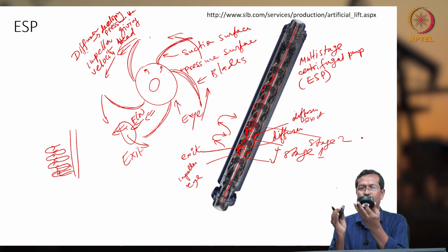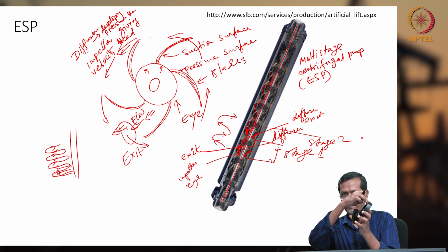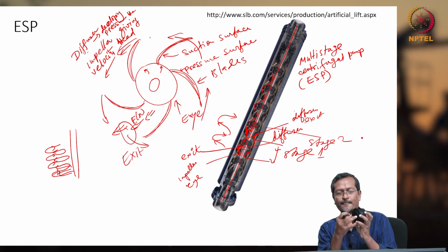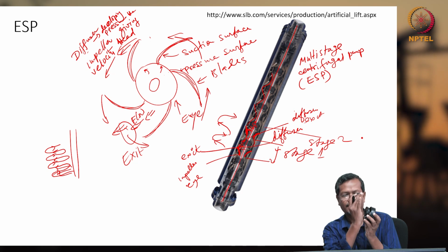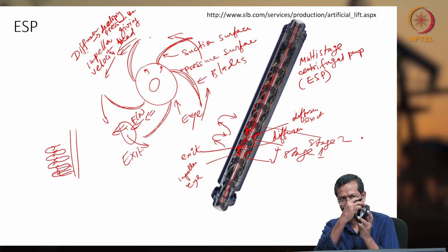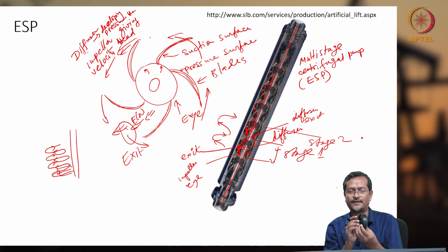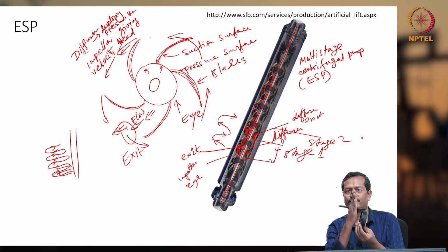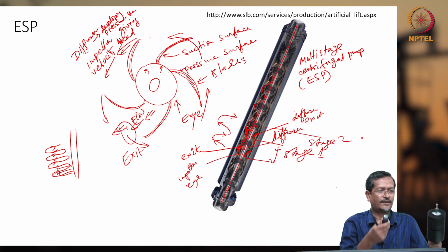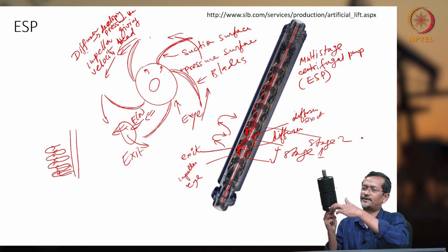I have the impeller, and the diffuser is this white part you can see. So fluid exits from the impeller, then enters from the top of the diffuser, and goes nearby the shaft. It will be connected like this. The impeller sucks fluid, going vertical, then exiting from here. After exiting, it will be entering. This white portion has a hole here. So from here fluid enters, goes through this, and exits from here. So this is your impeller and diffuser. One stage: fluid entering, going vertical, entering the diffuser, and coming axially again. Again the next stage will be there. I'll have another stage.